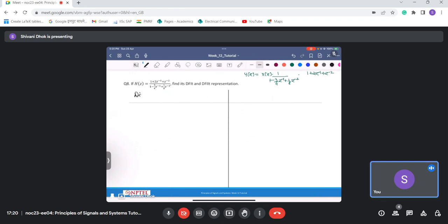So here I have my direct form 1 transpose. Here I'll draw direct form 2 transpose. So I have x(n) here, and it will get added to a delayed and scaled version of this factor.